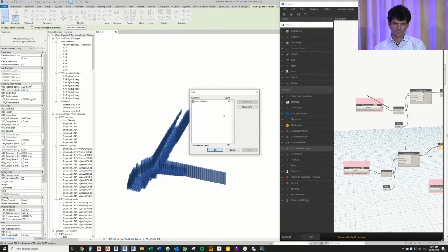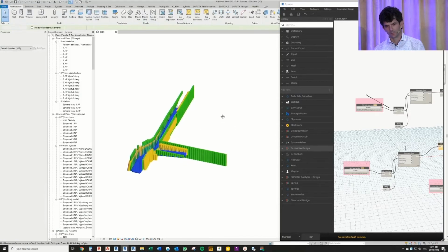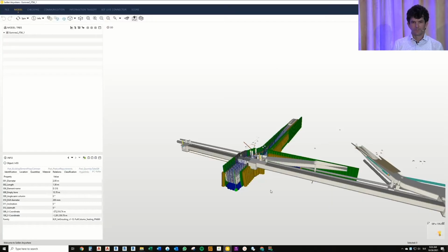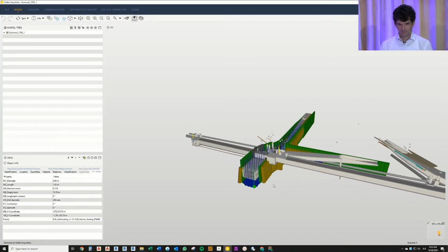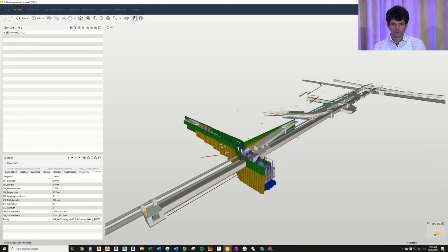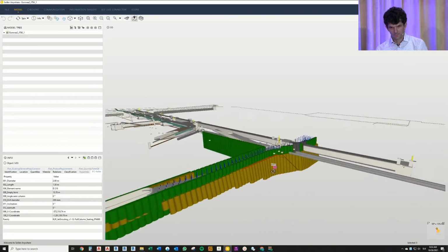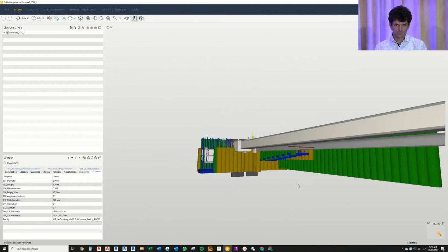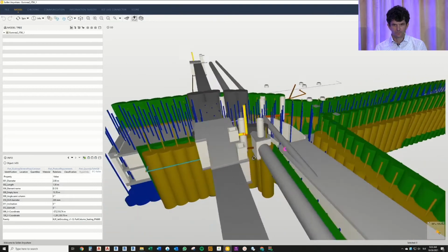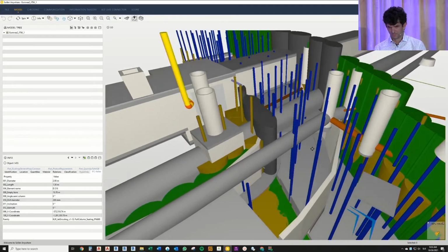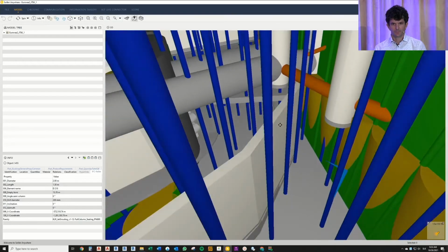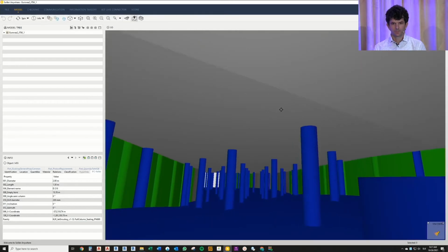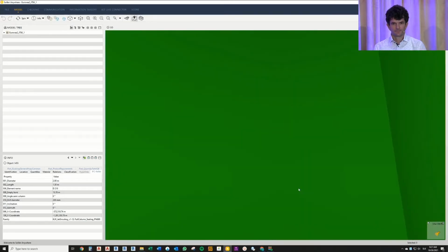There was approximately 500 components. If we did it manually, we would definitely made a mistake somewhere. Then we created an IFC file and we loaded the structure there so that the contractor can check any errors or collisions and check every component separately. So they would be able to click on any components and they would be able to check the parameters of each of them. So this is a very visual tool. It's a great aid. This is how it looked like.